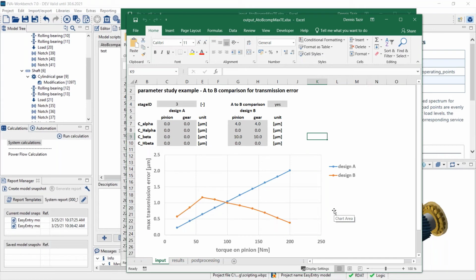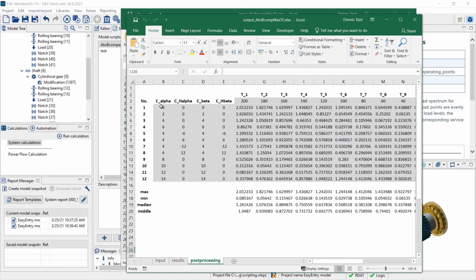Now, if you're doing a very smart scripting, and by the way, I forgot to explain, the scripting is JavaScript. It's very simple to use, I think. It's easy to learn by yourself. And with the scripting, you can specify loops and specify that all the tolerance combinations will run one after the other. And at the end, you can do post-processing like this one, where you write your specification of the modifications and then the results, one line below the other.